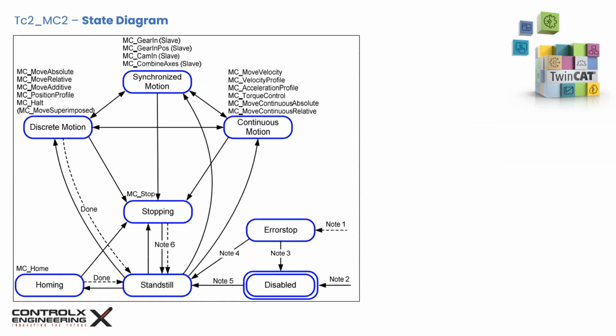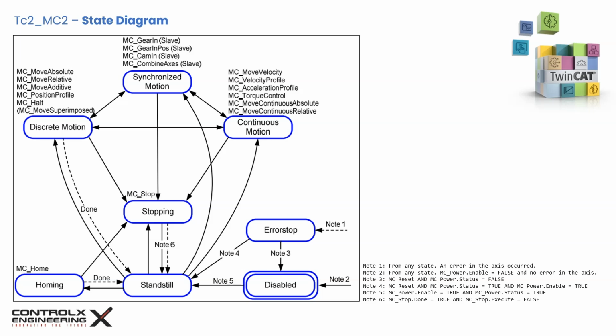The state diagram defines the behavior of the axis at a high level when multiple motion control function blocks are simultaneously activated. This combination of motion profiles is useful in building a more complicated profile or to handle exceptions within a program. The basic rule is that motion commands are always taken sequentially, even if the PLC had the capability of real parallel processing. The axis is always in one of the defined states. Any motion command that causes a transition changes the state of the axis and modifies the way the current motion is computed. A change of state is reflected immediately when issuing the corresponding motion command.